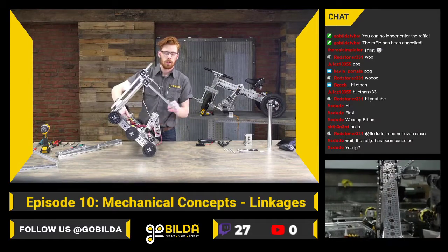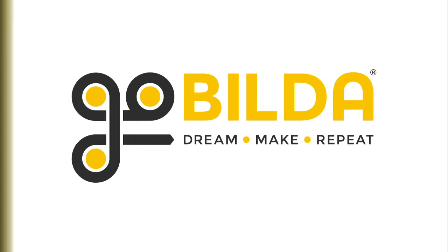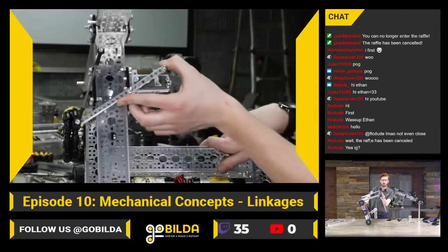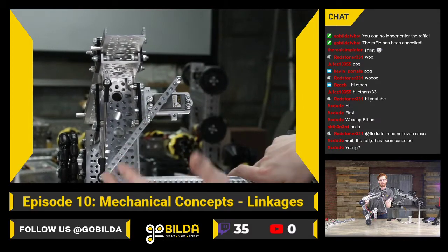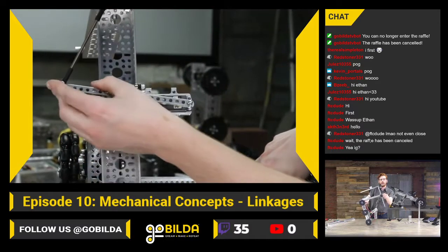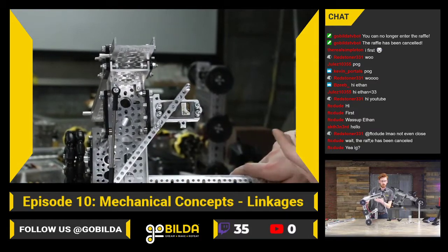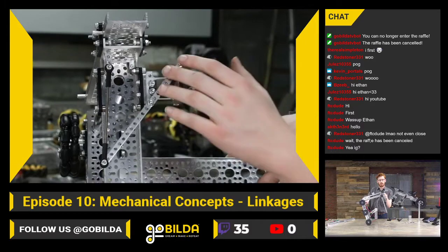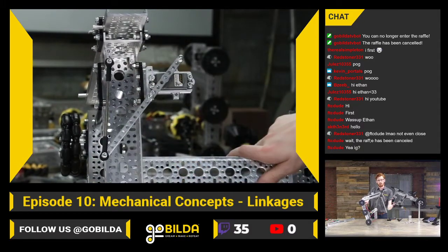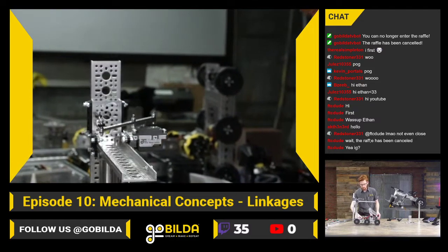You've got essentially an object that you want to travel linearly, like this slide here. And you have a servo arm that'll give you a lot of mechanical advantage. And the exact amount of mechanical advantage, so the torque to speed, or in this case, thrust to speed ratio, will change depending on where you are in the stroke. And we'll talk about that in just a few minutes here.